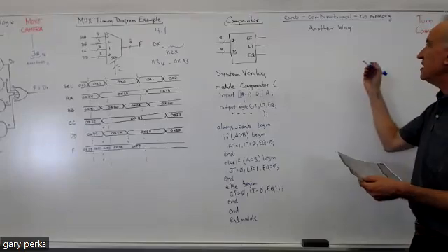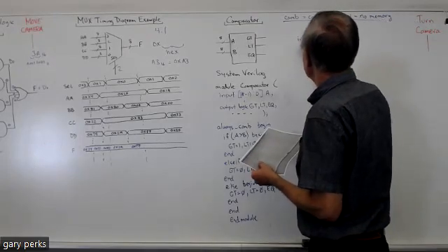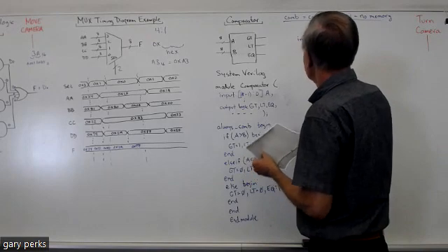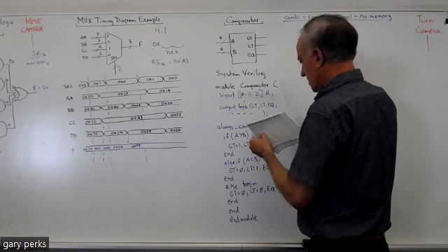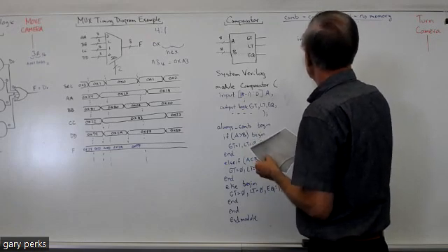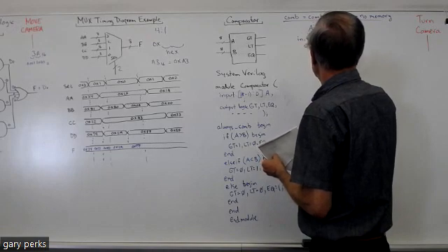If you want to initialize output values, you just do this. You go initial, and then begin, and then you would just list your outputs and set their values. So I'm just going to set them all to 0.